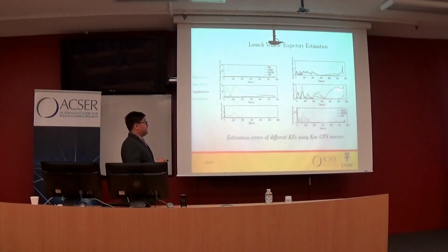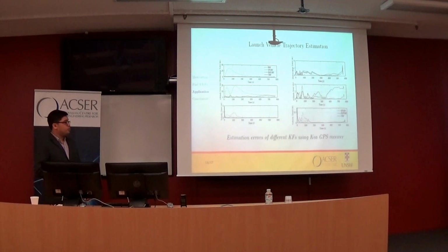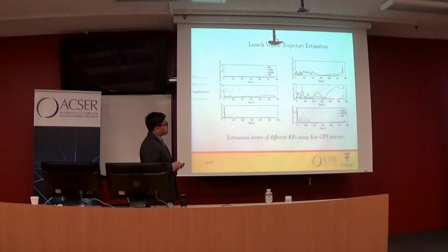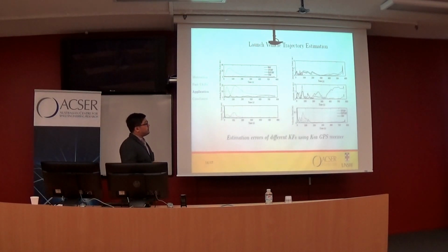But the interesting thing is that here the unscented Kalman filter performance is worse than the new SPUKF and ESPUKF, which I think is because of less noise. UKF tends to work better within a higher noise level. In less noise, the smoothing effect of UKF decreases. That's speculation. It's not well proven yet.